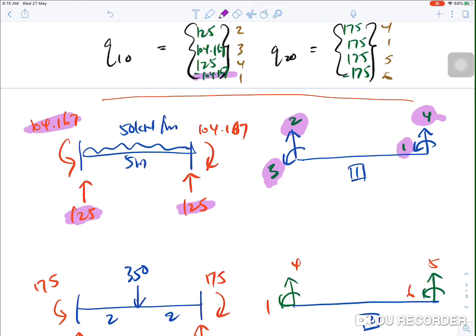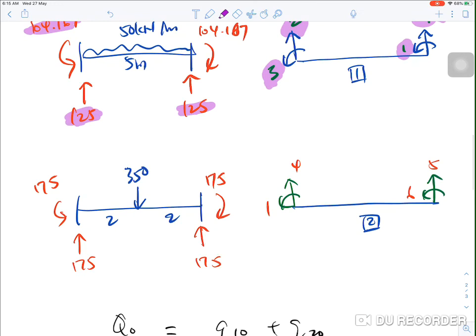Okay, we will do the same for element number 2. Element number 2 consists of a vertical load that is subjected on the member at the middle, at the center. So we calculate the vertical reaction as well as the fixed end moment using the formula given in appendix page 3. Okay, and the other one is the degree of freedom for element number 2. It is 4 for y, 1 for z, for the near node, and for the far end node it is 5 6.